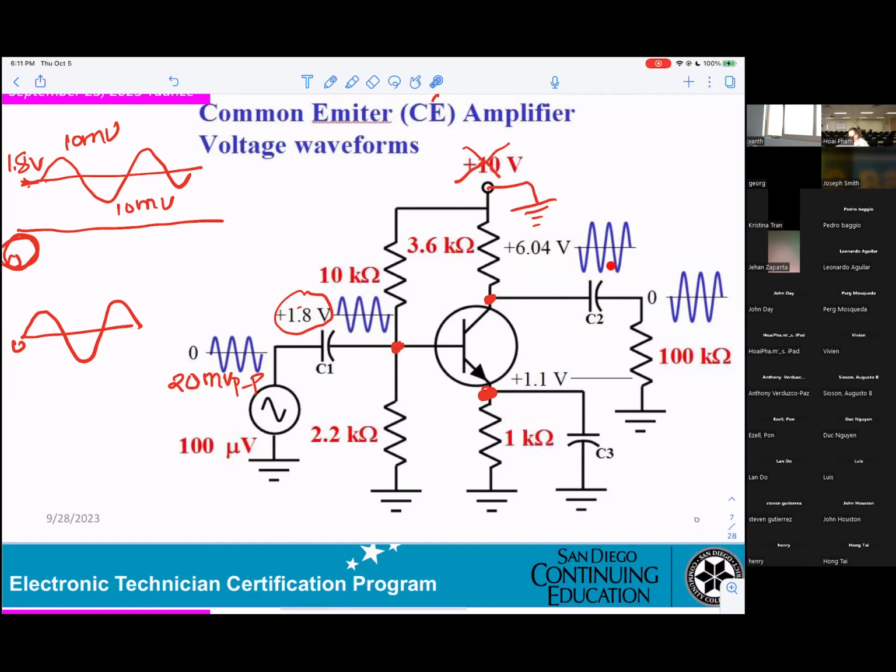And you know the problem with the capacitors C3, C2. They're supposed to block DC, but they don't. That's why you can change C2. When you're looking at the signal at the meter, do you see any sine wave at this point?